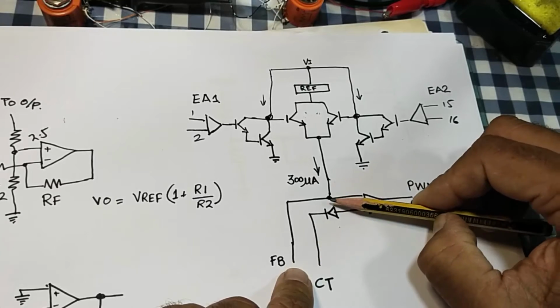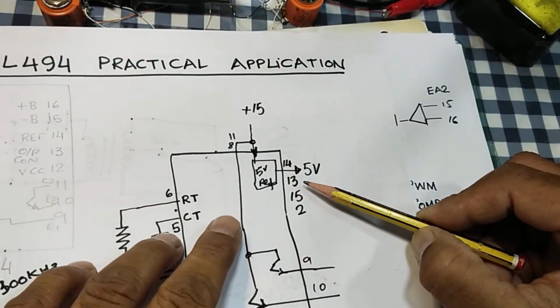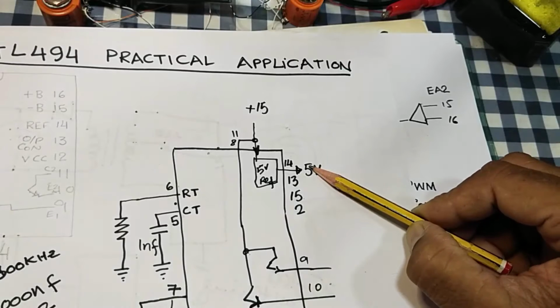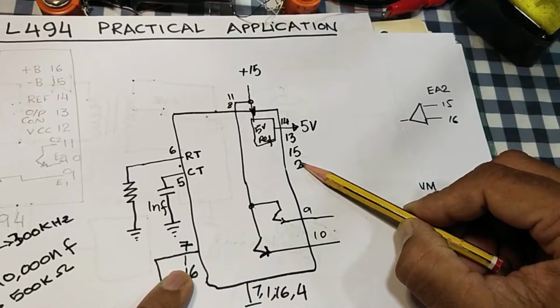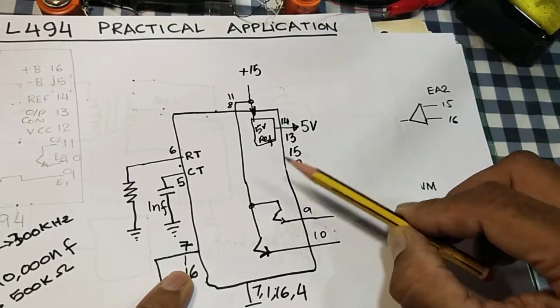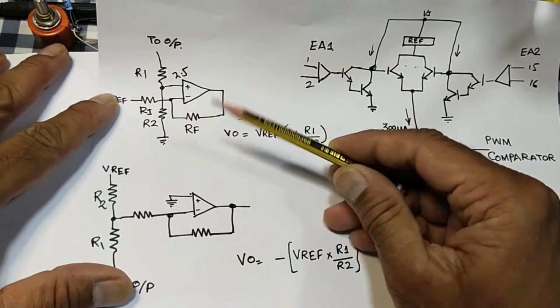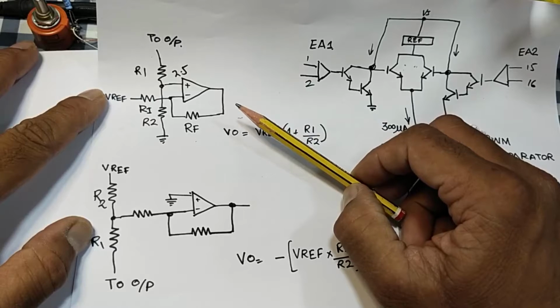on the feedback resistor. First of all, from our last setup, we will remove pin number 15 from the 5 volt reference, and we will remove pin number 16 and 1 and pin number 2, and today we will program them independently, because in TL494 there is only a single-ended power supply, that is V reference.